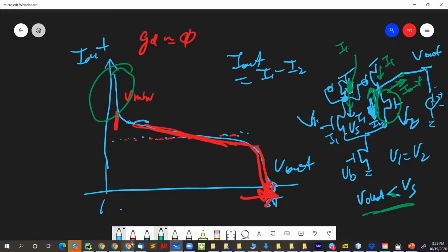Oh yeah, okay, Nicola, your question. Yes, if you make V2 greater than V1, then I2 is greater than I1. And so the voltages will settle in the place where in the end the currents all balance out. So it wouldn't be the I2 and I1 corresponding to all these transistors staying in saturation. Because when VS is not where it should be, this IB current will move. It's no longer at the saturation IB current. In fact, it could go very close to a small current, much smaller than IB. So you can think of this now as like IB prime or something.